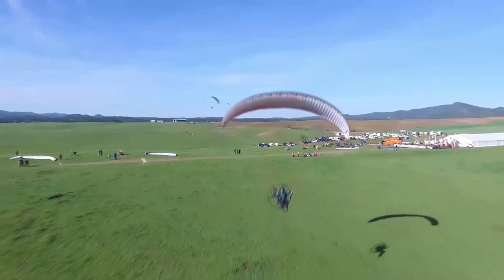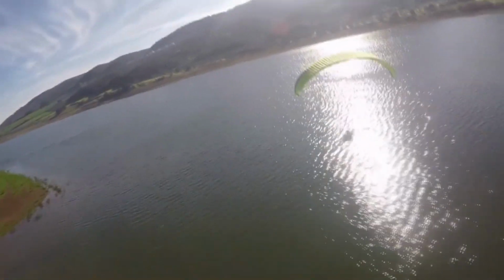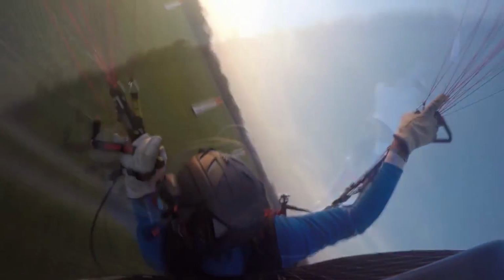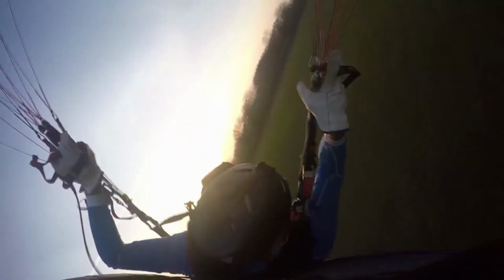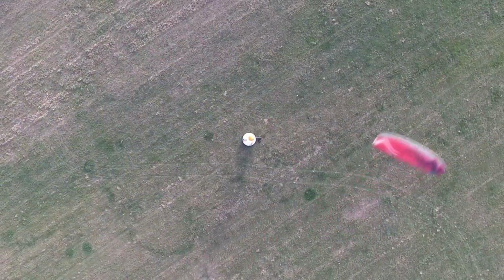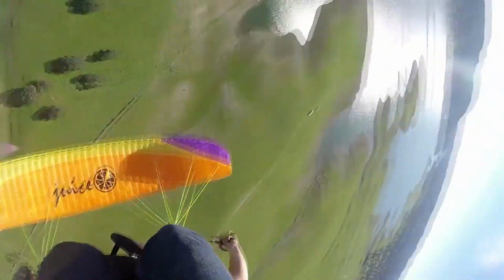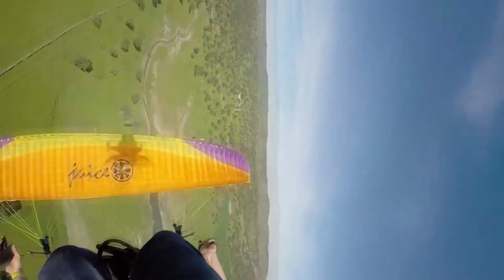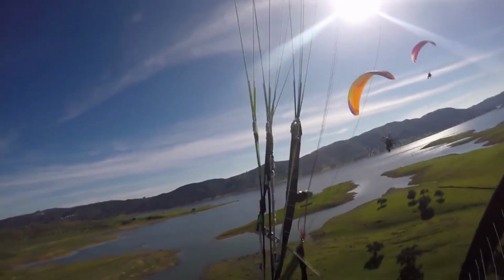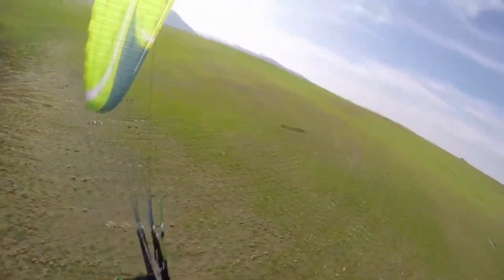Basic propeller principles. The WSC aircraft propeller principles are similar to those found in the Pilot's Handbook of Aeronautical Knowledge, except there is no corkscrewing effect of the slipstream and there is less P-factor because the carriage is generally flying with the thrust line parallel to the relative wind. The wing acts independently, raising and lowering the AOA in speed. This was introduced at the beginning of this chapter when angle of incidence was defined.